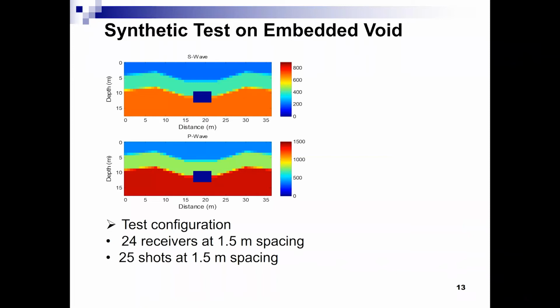Later on, we'll talk about frequency domain inversion in 3D. Here we do time domain, because in time domain we have a consistent magnitude. Initially, we did frequency domain, and the magnitude from the waveform generated by the sledgehammer is not consistent. We have the peaks up and down everywhere, so we cannot select a consistent component to do inversion. So time domain helps.